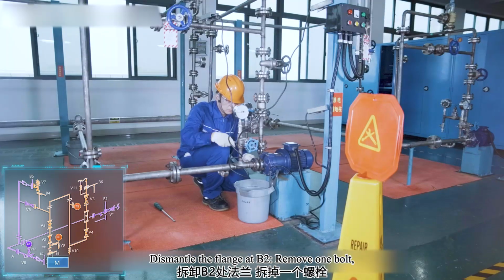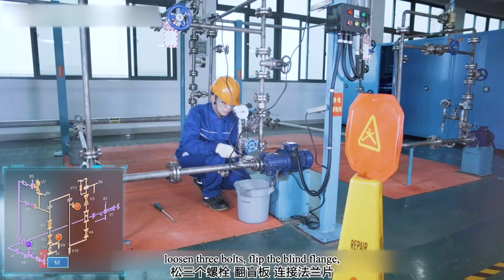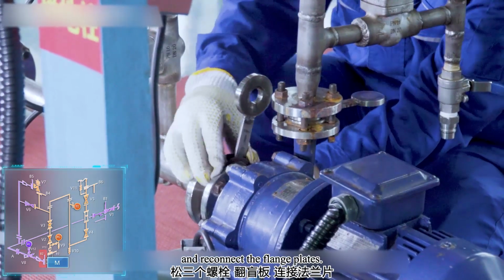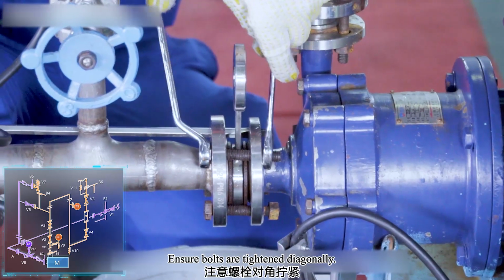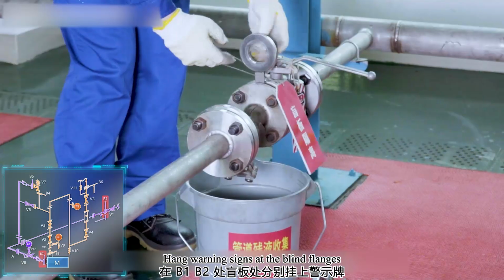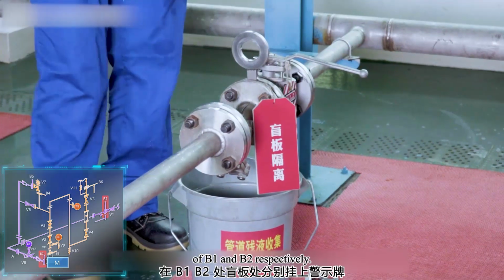Dismantle the flange at B2. Remove 1 bolt. Loosen 3 bolts. Flip the blind flange and reconnect the flange plates. Ensure bolts are tightened diagonally. Hang warning signs at the blind flanges of B1 and B2 respectively.